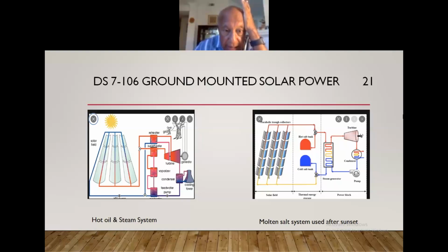So this plant has to be started every morning. So imagine that when the plant is being started, the water system in these heat exchangers is stationary and cold. However, they have to start this pump and start heating up the oil, which slowly rises in temperature, 2, 3, 400 degrees Fahrenheit. And there is a huge temperature differential between the hot oil side and the cold water side.